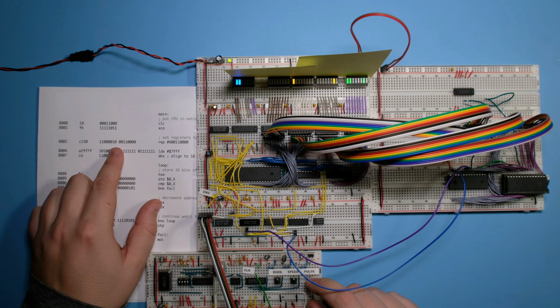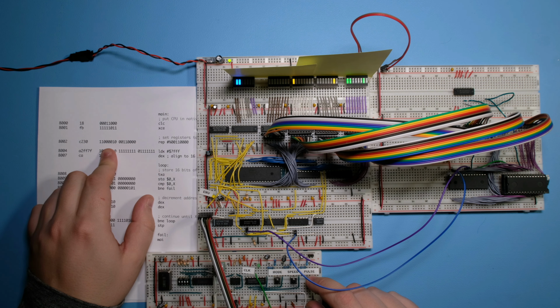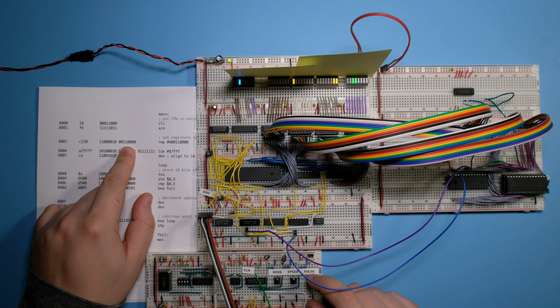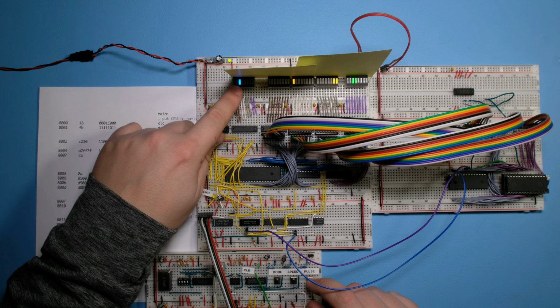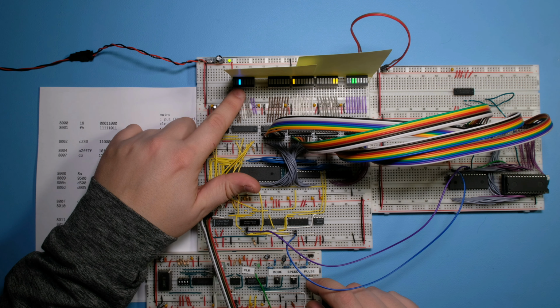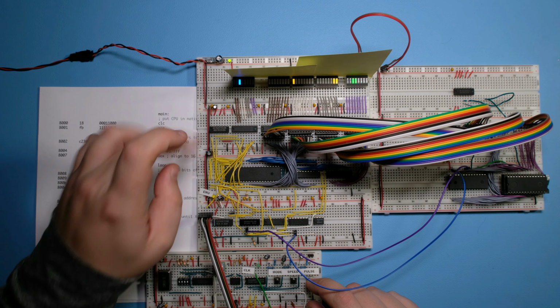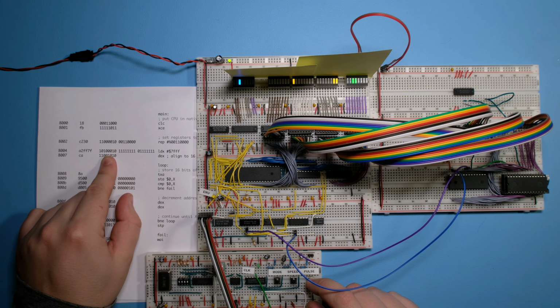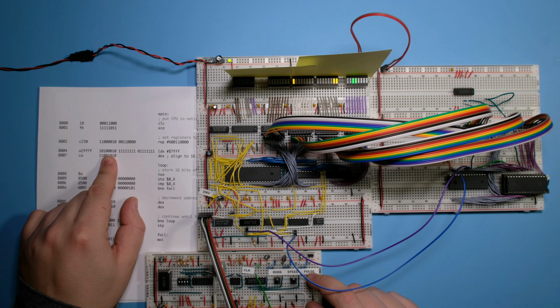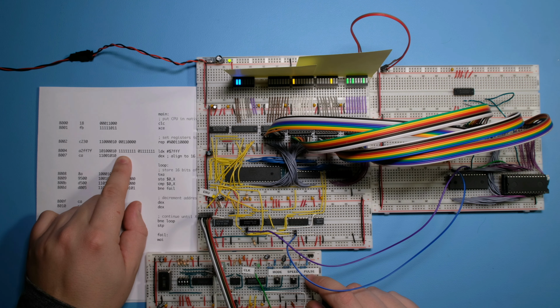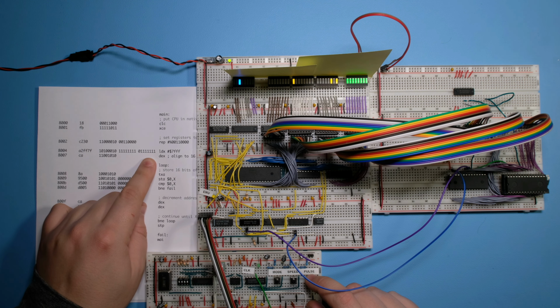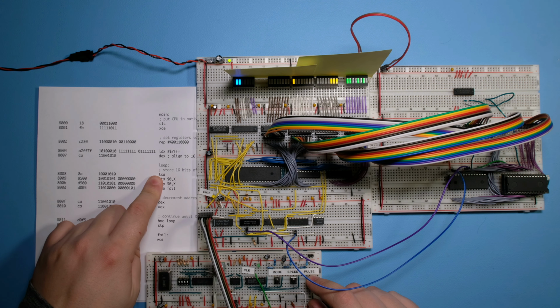Then we are going to enable 16-bit mode in the CPU. This is the REP instruction, which we are loading here. And then we are going to load the immediate, which is here. And so this works. You can see only a valid data address has lit up here. And so this is not an opcode, so it's the immediate. Then we are going to set X with the end of RAM. So this is what we are loading. And then we are going to load FF and then 7F. And then we're going to the loop.